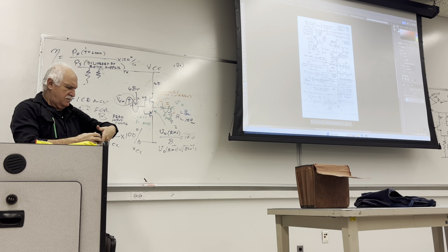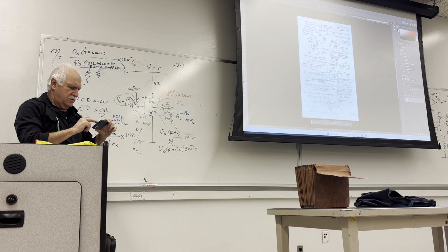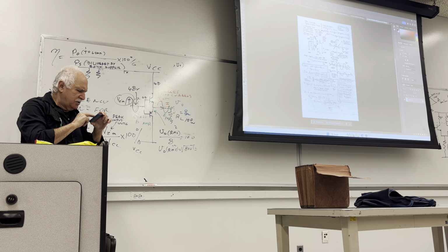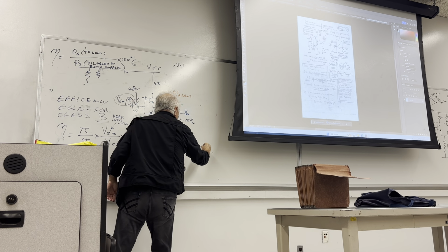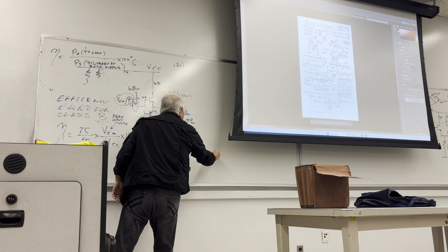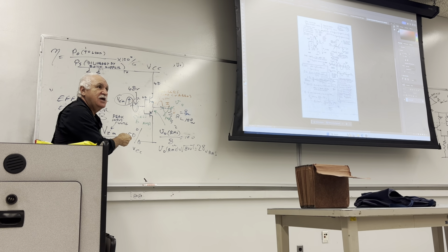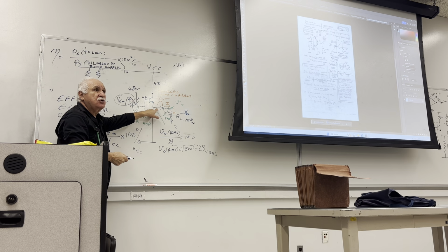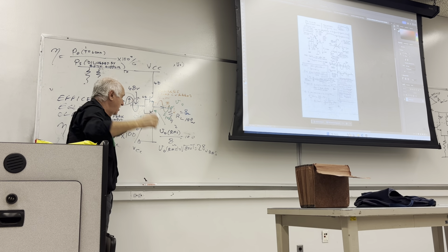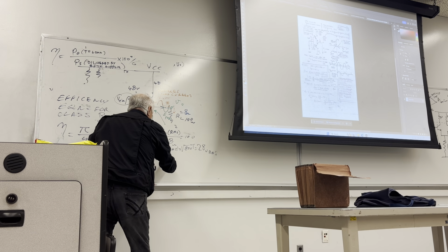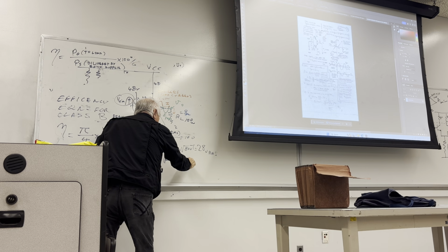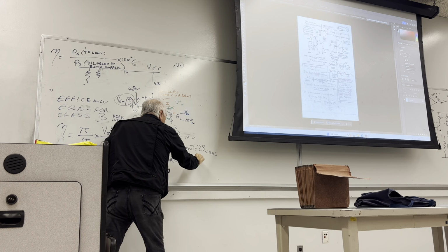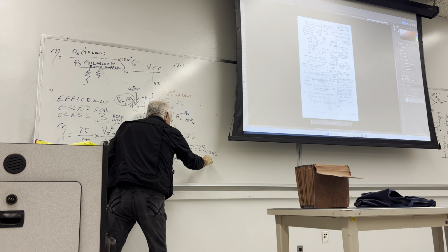Here, 800 square root, where is it? 28 volt. So this is 28 volt. But what is that? 28 of RMS. It's not yet the peak. So what is the peak in here? Because the transistor should be able to go, right, to the peak. 28, so VO peak, which is approximately the same as the supply, should be radical 2 multiplied by 28.